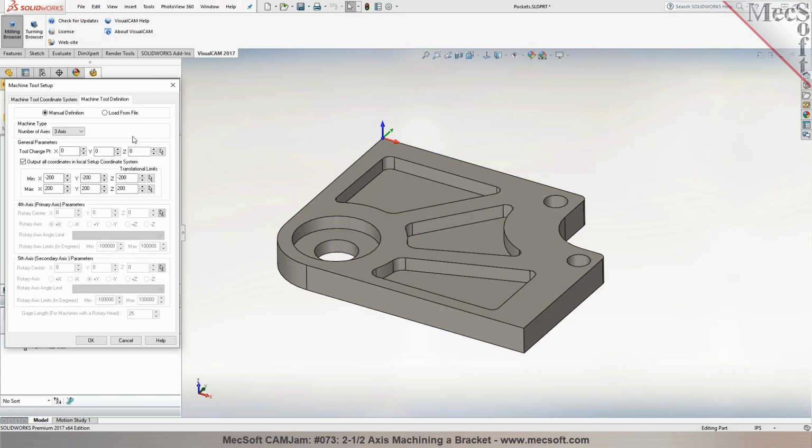Our standard configuration offers 2 and some of the 3-axis toolpath methods. The expert configuration would be ideal for basic 3D milling plus rotary 4-axis milling. The professional includes 2 to 3-axis, also 4-axis, and programming from multiple orientations, which is known as 3+2 machining, or it could also be called indexed 5-axis machining if you have a 5-axis machine tool.